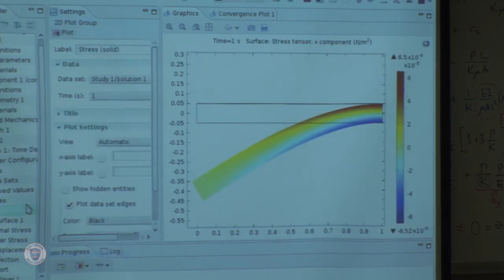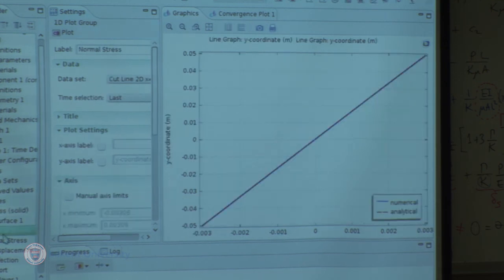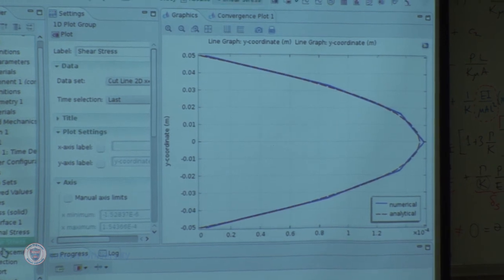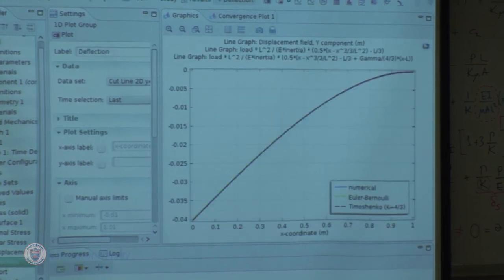even thinner. Okay? So this is a better, let's say, deflections, by the way, here they are magnified by 10. So in reality, it's less, small deformation, relatively small rotation. Okay? So this here is a case where we have really almost, for all practical purposes, excellent match of shear stresses, normal stresses, X displacement, deflection, etc. In fact, even the beam theories are doing very well because indeed it's so slender that the match is excellent. It's expected to be excellent.